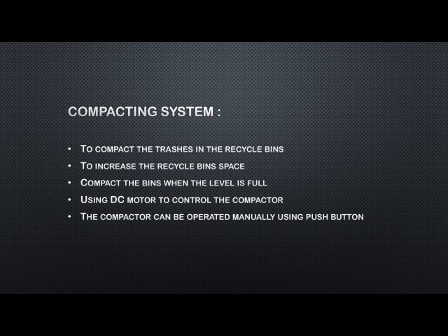For the compacting system, it's operated to increase the space of the recycle bin. The system uses a DC motor to control the compactor to compact the trash or waste in the bin at the preset level or when the level is full. It can be operated either automatically or manually using a push button.